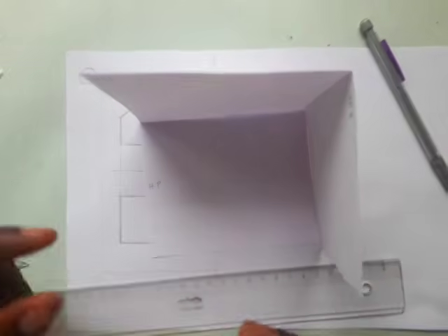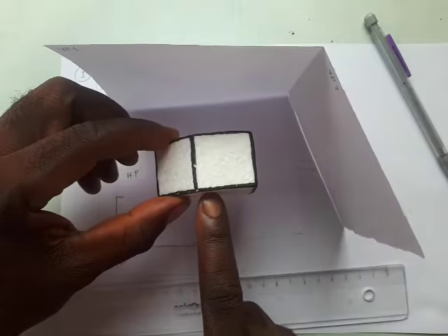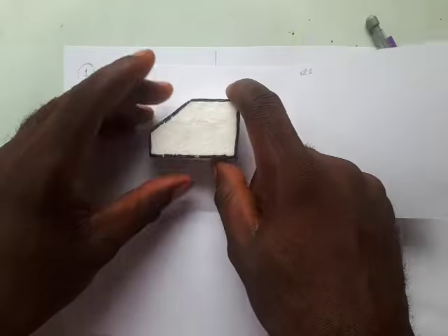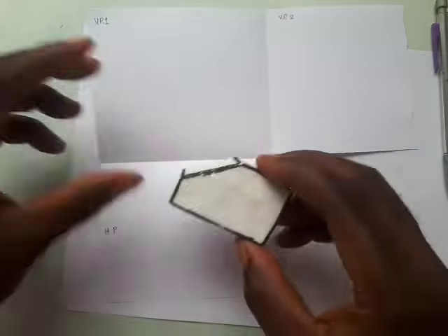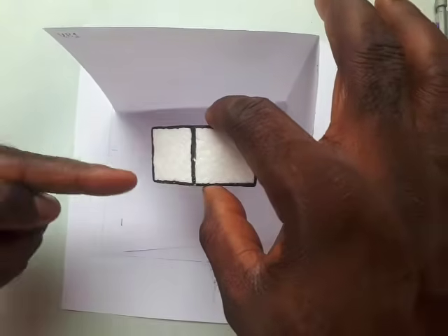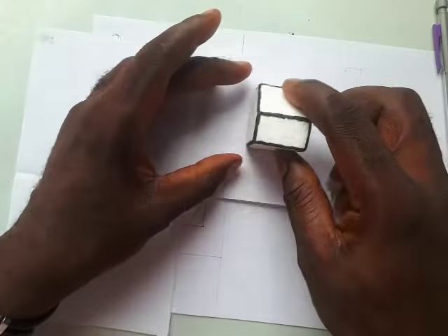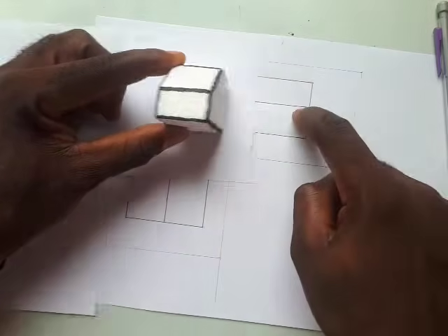Okay, so if I spread this out like this, now remember, whatever I view in this form, I'm going to draw here, so that's my what? Elevation, which is what you're seeing here. Let's go back again. If I move to this side, remember this is in space, and I view, whatever I view, I will draw here, which is my end elevation, which is what you're seeing here. A rectangle and another one. All right, and the plan.